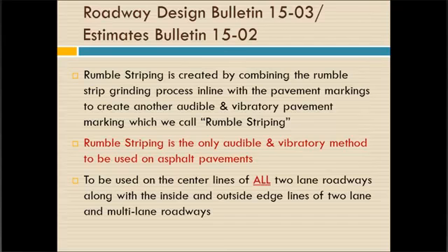It's so close to rumble stripe, people did not notice the slight difference. Now, rumble striping is created by combining the rumble strip grinding process in line with the pavement markings to create another audible and vibratory pavement marking, which we call rumble striping.